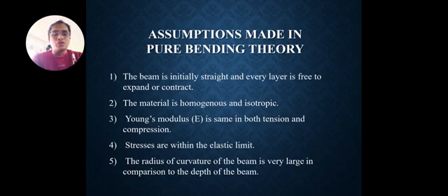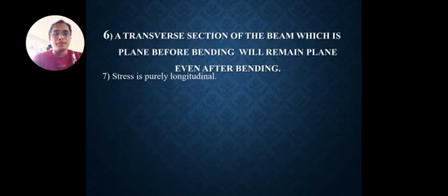The radius of curvature of the beam is very large in comparison to the depth of the beam. A transverse section of the beam which is plane before bending will remain plane after bending. Stress is purely longitudinal.